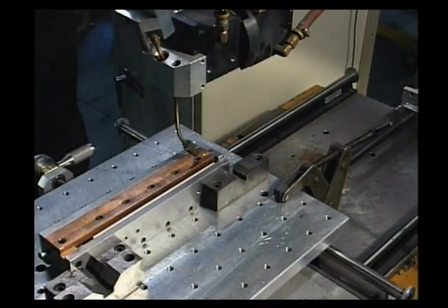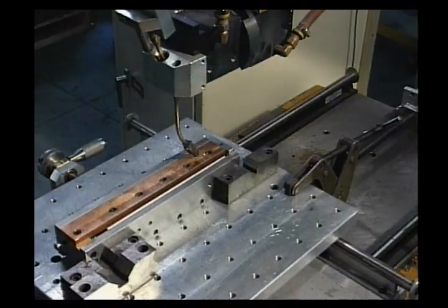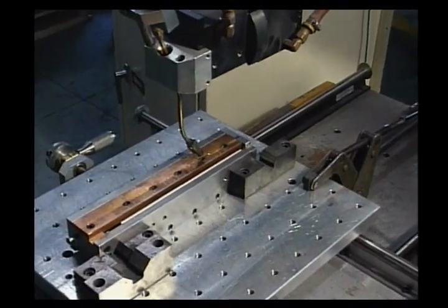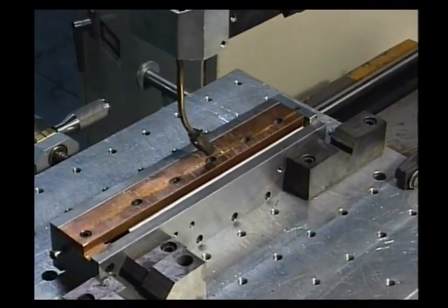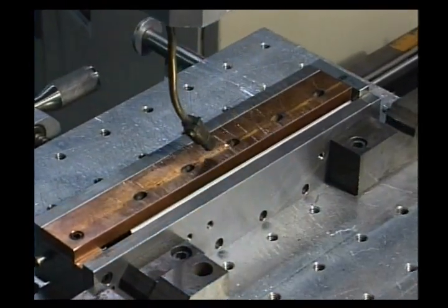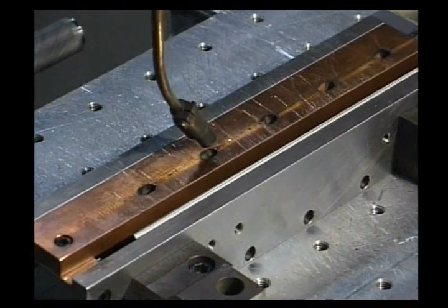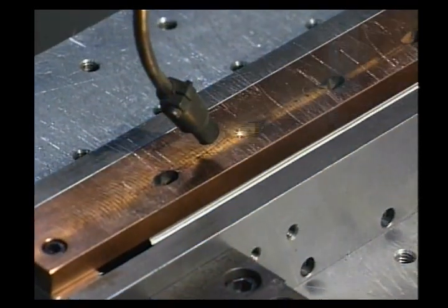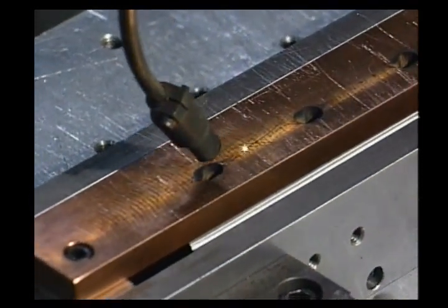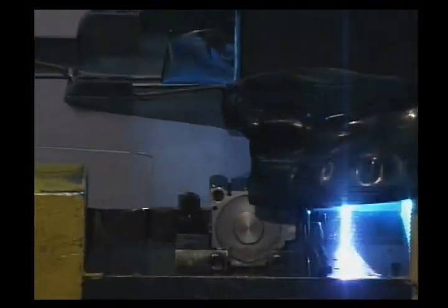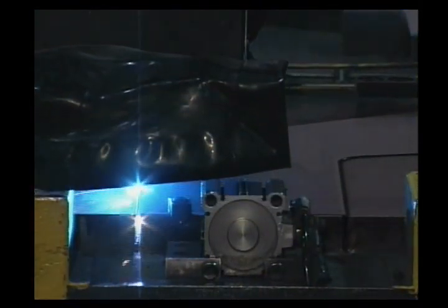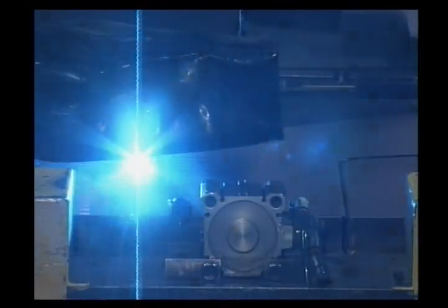Welding speeds are usually much higher than other welding processes, thus limiting heat-affected zone size and workpiece distortion. In addition, because of the intense, precisely focused heat, welds can be quite deep. Also, welds can be made in confined regions and between dissimilar metals. Laser beam welding systems are used in many industries and are typically fully automated and computer-controlled.